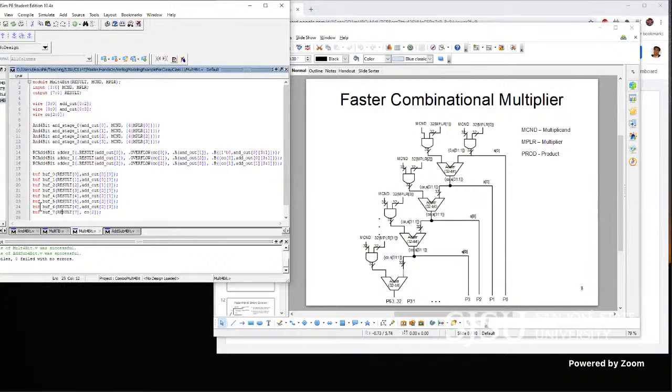It bumps up the strength of the digital signal. For a physically long running wire from one logic place to another place, sometimes we insert a buffer to strengthen the electrical signal value on the line, but it doesn't have any logical consequence or logical operation in the circuit. Anyway, that's a different story.